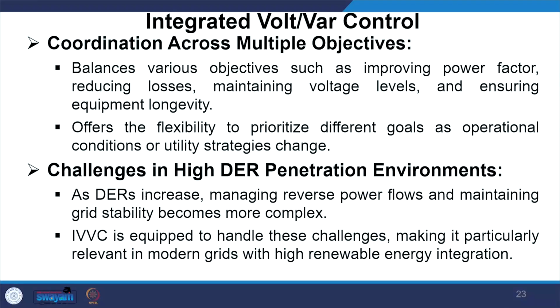Now, there are a bit of challenges due to high DER penetration. As DERs increase, managing reverse power flow and maintaining grid stability become more and more complex. IVVC is equipped to handle these challenges, making it particularly relevant in modern grids with high renewable energy integration.